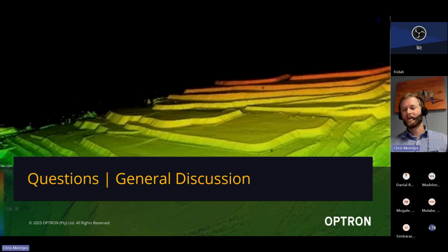But when you're underground and you have a tunnel or a stope, or anything where it's completely encapsulated by points, TBC will take that as one very noisy surface and try and mesh through it, whereas RealWorks, having no projection plane, will be able to run a mesh around and generate a solid like you would in other software packages such as Deswik or MicroStation. So to answer your question, there's a lot of the point cloud functionality from RealWorks in Business Center, but there are one or two aspects of RealWorks that aren't in Business Center yet.